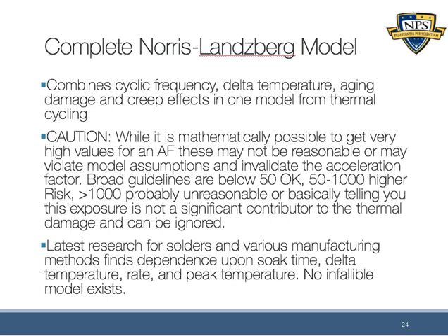So if we're going to do an acceleration factor of 1,000 or 5,000, then we're getting to the point where there are some natural limitations here, right? You can only do so many temperature cycles and actually have your product achieve the high and low temperature. You can only do so many of those in a set amount of time. So then the reality is that you're naturally going to be a little bit limited. And if you try to force it faster, your product will not achieve those high and low temperatures. You won't have enough dwell time, and so you won't be able to actually get to it. It won't take on the amount of damage expected, and you'll have to void your results.